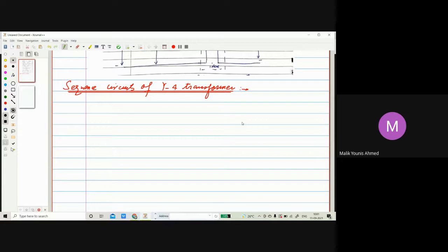Also, we have seen that there are 5 to 6 possible combinations. We'll see 5 combinations normally, and I will be explaining one combination in detail. Then the rest I will just refer to, and we'll draw the zero sequence networks for those. Arrows on the diagrams will indicate the possible paths for the flow of zero sequence currents. Absence of an arrow will indicate the transformer connection is such that zero sequence currents cannot flow.